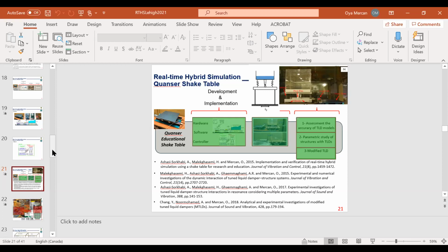So far, as Tommy indicated, the way that we are currently doing it is with a DLL, which is converting a Simulink model to an executable file to be executed on LabVIEW. And we can model the nonlinearity there also. But in order to make it a bit more efficient, we are right now looking at some parallel computing techniques to implement a simplified version of a finite element analysis on the FPGA itself.